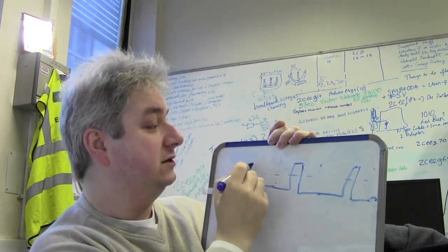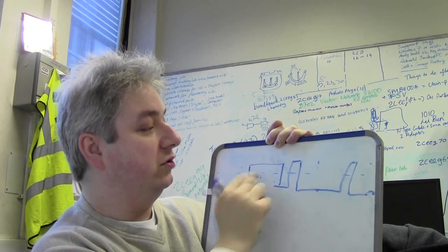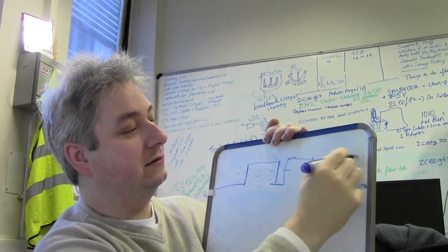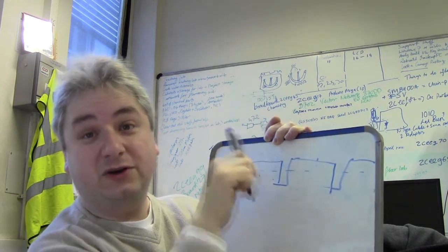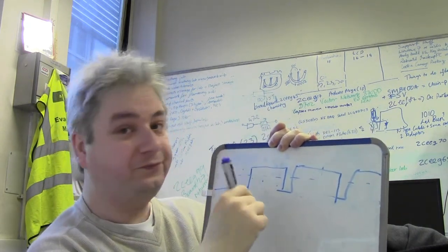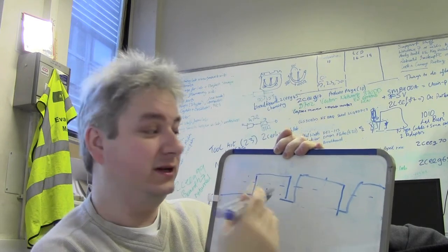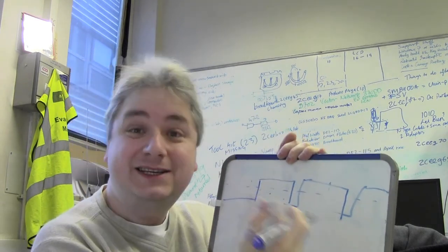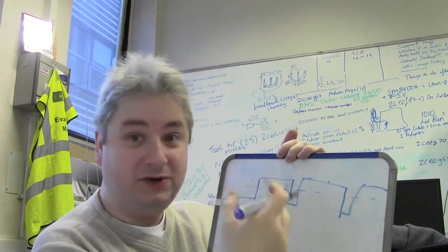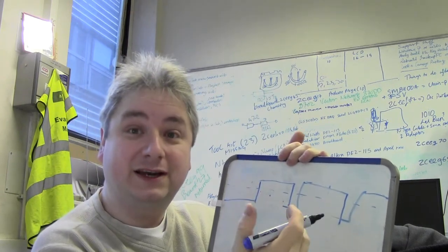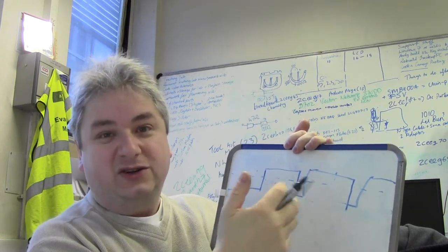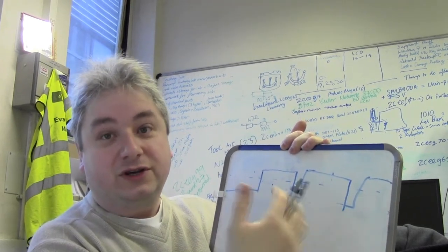And likewise, you can have it more on and less off, which means you've got more power. Now, yes, you can do this. You can pulse width control LEDs. That's how you can dim an LED, and you can get different light levels out of an LED without having to do much analog control. You can do it all in digital.